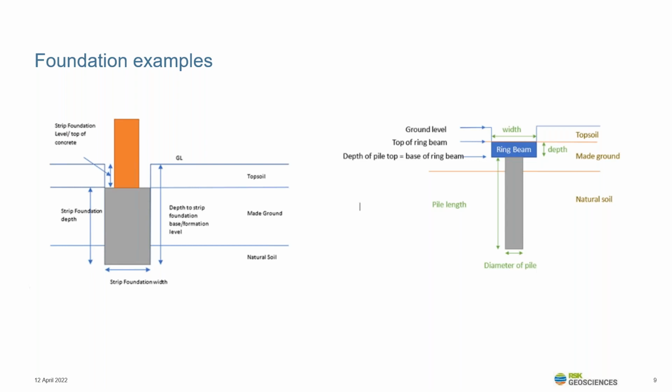Other extra information is always great. The percentage of steel reinforcement can also be included, and where it's not available, it can default, and it's something that we can modify throughout the design process. The final information that's included is for waste. This takes a ground model, so it takes topsoil, made ground and natural soils, and can record the percentage reused on-site, percentage used off-site and percentage that goes to landfill. The landfill option can also select between hazardous and non-hazardous.